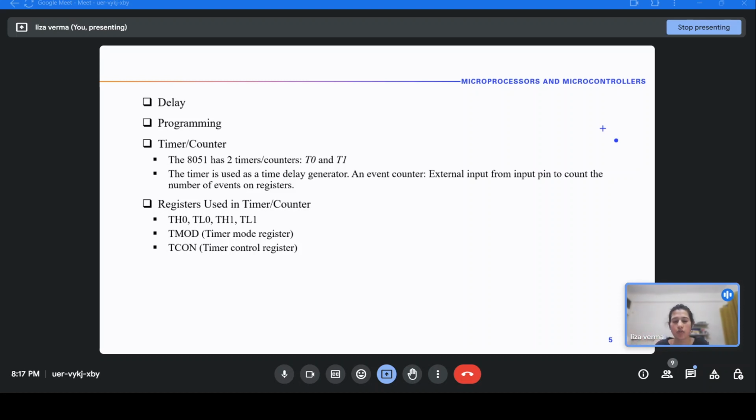So whenever a car is going to pass, the signal will go low, and that will create a count for you. The number of times the signal goes low creates a count, which means the clock does not have a fixed frequency. An event can happen anytime.